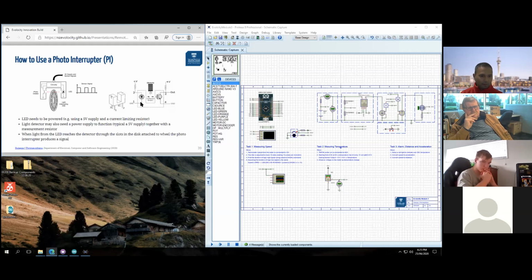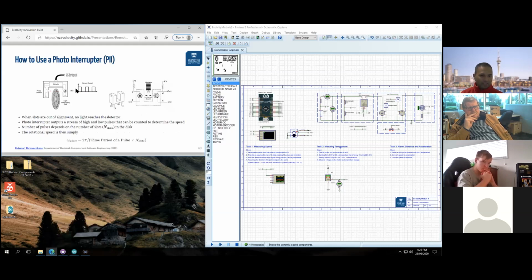Right. So now moving forward, assuming that we have n number of slots in this wheel that you would make, this sensor, the optical tachometer, you can easily buy. Les has quite a few of those that we used in previous years. You just buy it, and then you go to your manufacturing lab and make a disc that has these holes. You can have 10 holes, you can have 5 holes, you can have 1 hole. With more holes, you can work out things a bit more accurately. But for a cart that's traveling at speeds like what you would have in the race, it doesn't really matter. Even 1 hole is sufficient.